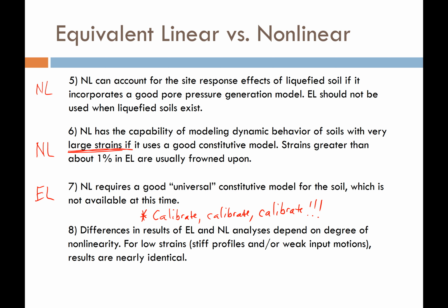For cases where the strains are larger than 1%, nonlinear analysis is going to be better if you have a reliable and validated constitutive model and a reliable and validated pore pressure generation model. So I would say in this round we probably have a draw.